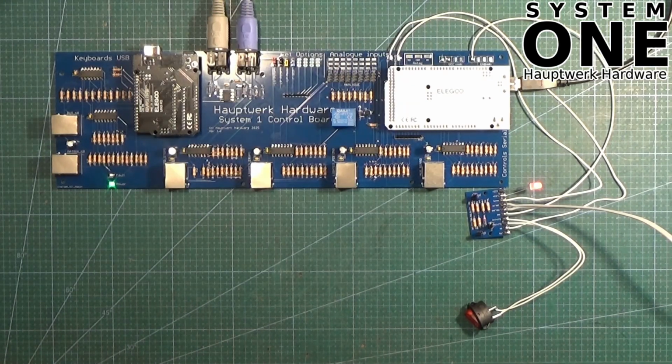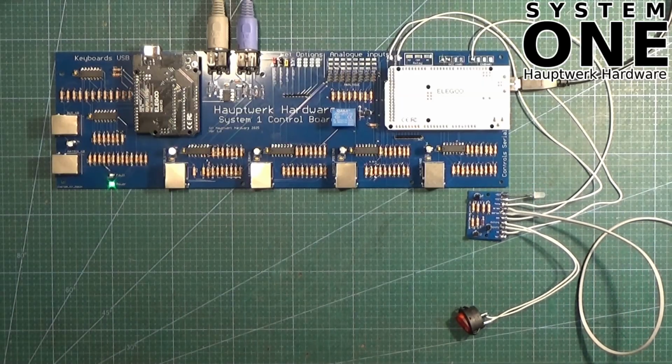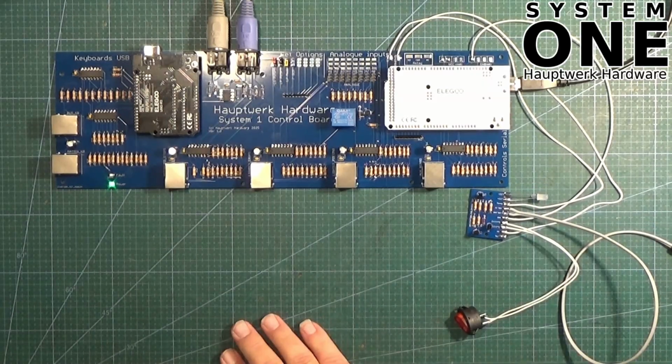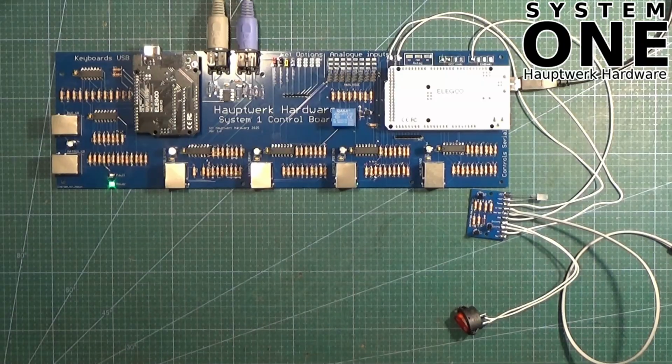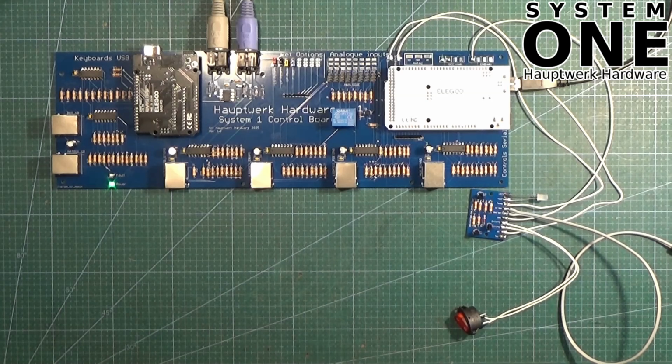So at this point now, the computer would have shut down, and the USB power would have gone off, which is our thing here. So obviously that would be equivalent to that, and the LED would have gone out. And you can see that no more MIDI has been sent now or anything else. So that's basically how the whole power management system works. It just requires 2 MIDI events. One of them is the event to turn the light from red to green and back again, which is note 100 on channel 11.